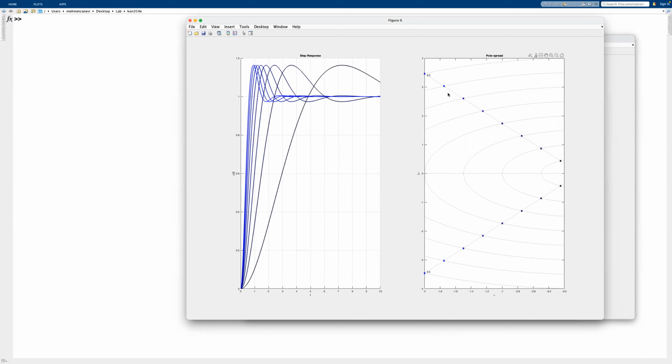Now, the interesting fact about this is the following. We have basically all the peak values aligned. So that means that the peak value doesn't change, and peak value transitions into overshoot because peak minus the value in steady state divided by the value in steady state times 100 gives us the overshoot percentage, and that wouldn't change if we have the same peak value, and we do. So certain zeta values will correspond to certain peak values, which will give us basically certain overshoot values.